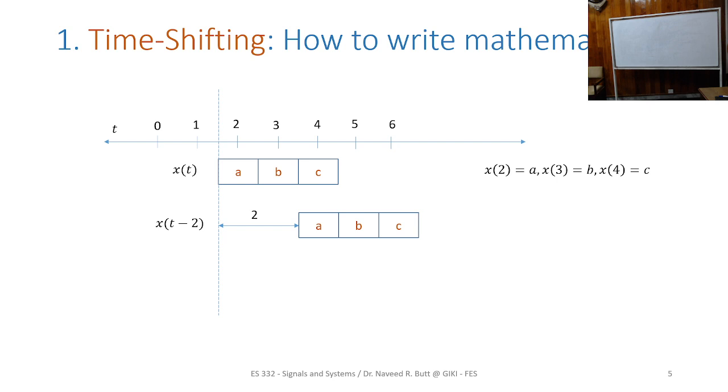Right. So what you want to do is basically in the offline mode, you get 10 values, right? And now you are giving output at this point. You can use the next 6 values, average them and give the output. So you use future values to process each particular output, right? You have to give 10 outputs, and in each of those outputs you can use the current value, past value and future value from your reference point. But again, physically it's not possible, right? We will come to that.